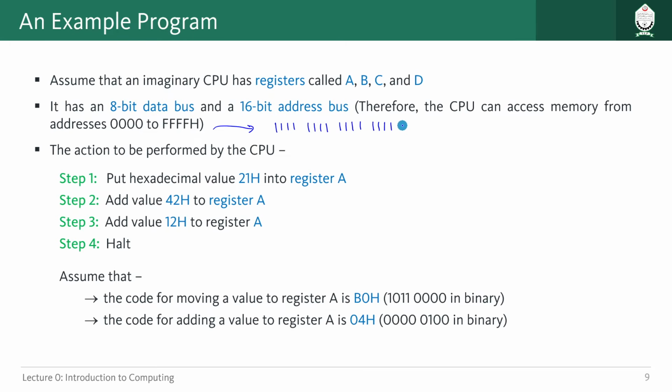This is also possible, right? So this is the last location. So because this is binary, we can write a B there. By this being hexadecimal, we mean this is the last location that can be accessed by the CPU, right? Because this is a 16-bit address bus.